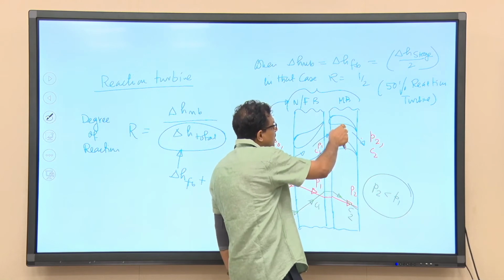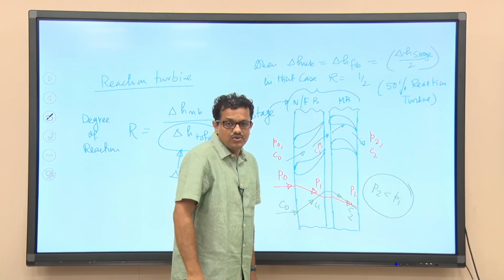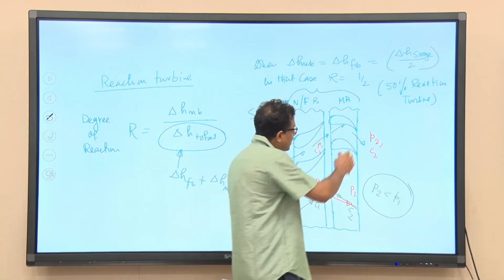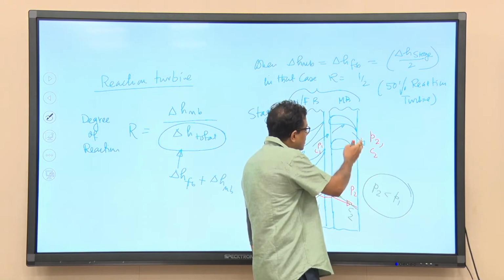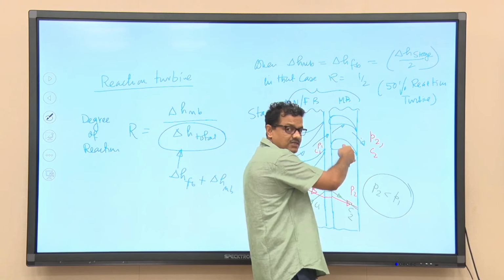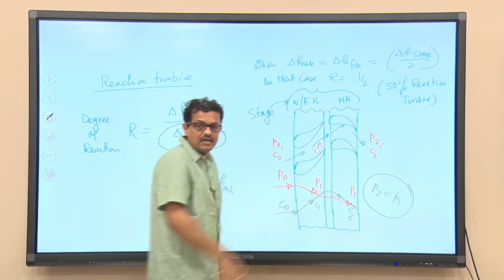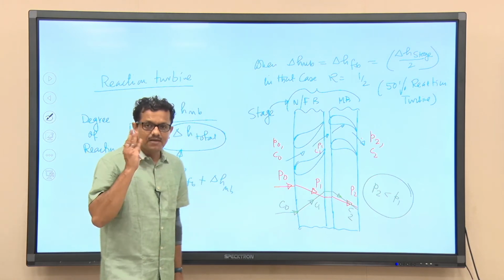Because of the shape of the moving blades, which is of nozzle shape, there is a relative increment in kinetic energy, and because of this a reaction force will be impressed by the leaving jet on the blades, in the opposite direction, Newton's second law. So, we are having the impulsive effect.